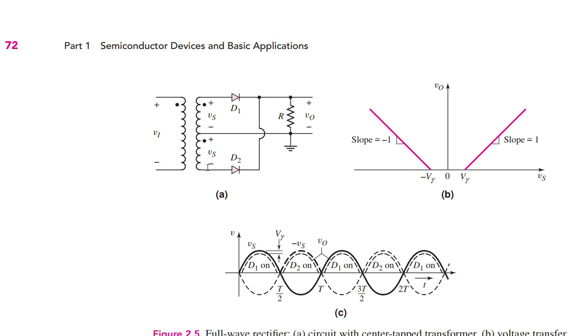in that case the largest reverse voltage will appear, because as I said for the half wave rectifier, the inverse voltage is the potential difference of the cathode side and the potential of the anode side. So if this voltage is at the maximum and this voltage is at the minimum, in that case the peak value of the inverse voltage will appear.